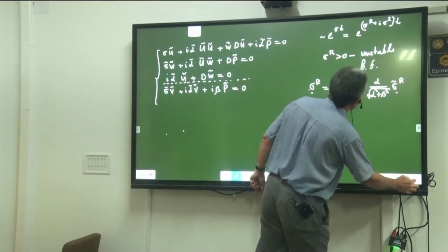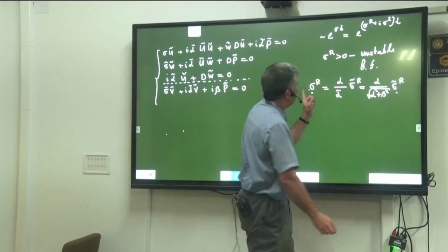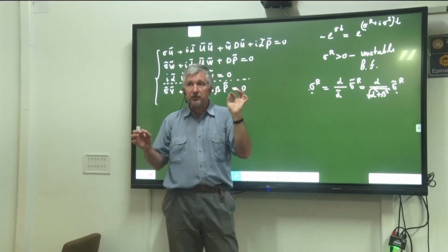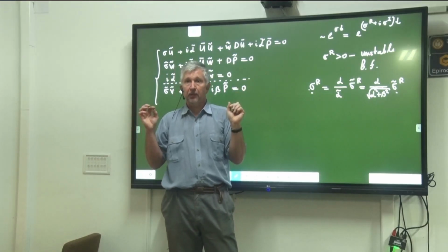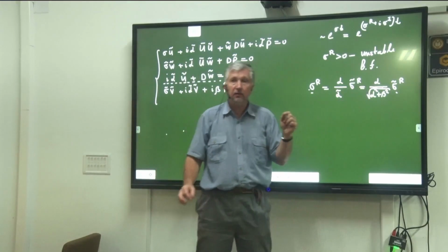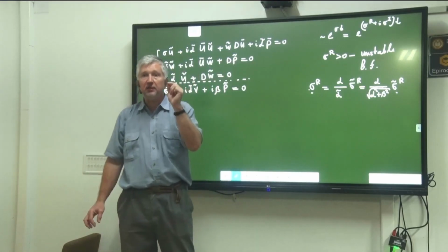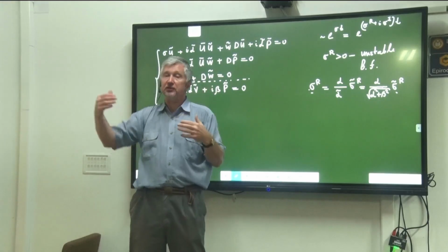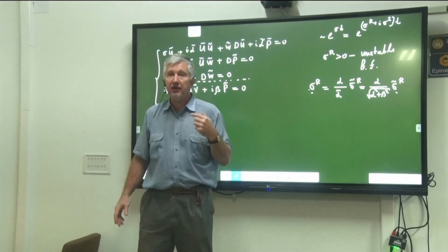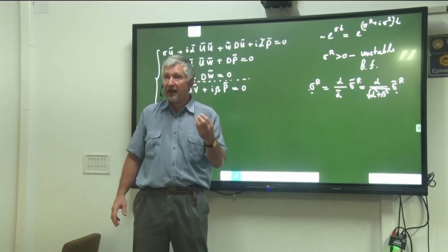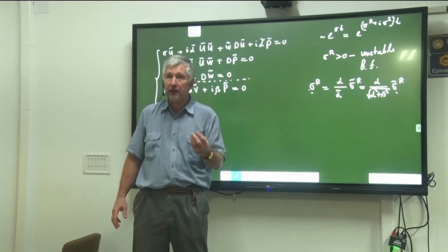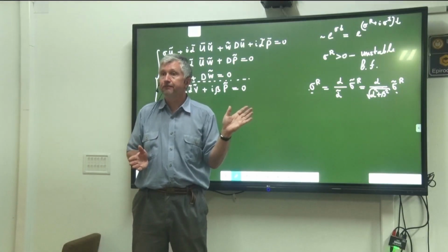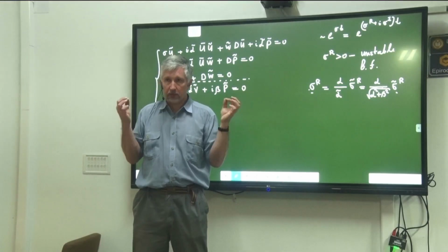Okay. But sigma tilde is what happens when beta is equal to 0 and v equals 0. So it turns out that sigma tilde, which corresponds to beta equals 0 and the two-dimensional case, when perturbations are chosen to propagate in the main flow direction, is always greater than the perturbation growth rate of three-dimensional disturbances. That is a fundamental physical conclusion.